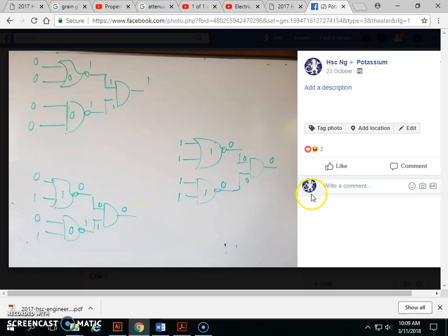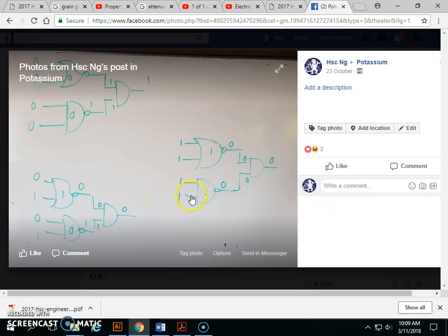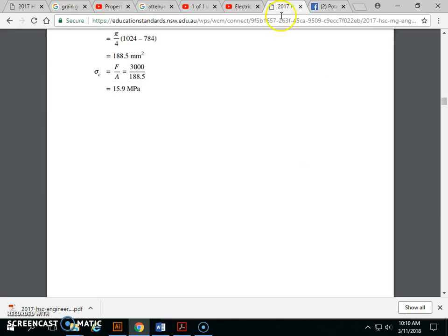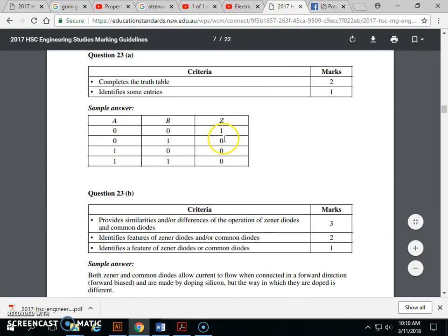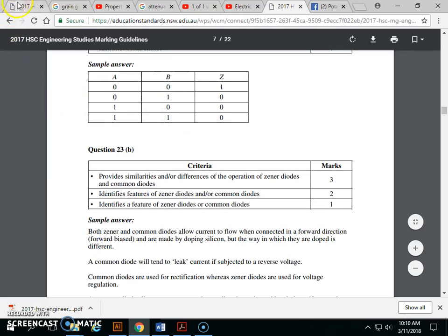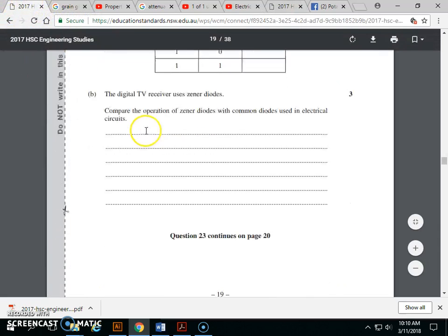Here, if we have all of the ones, well, the OR gate would have let them in, the AND gate would have let them in, but the NOT dot in both cases flips and says, nah, not allowed in. So if they're not allowed in here, the AND gate says not allowed in here. So the answer is 1, 0, 0, 0, yeah, all the zeros. Okay, no explanation there in the answers, it just moves on.